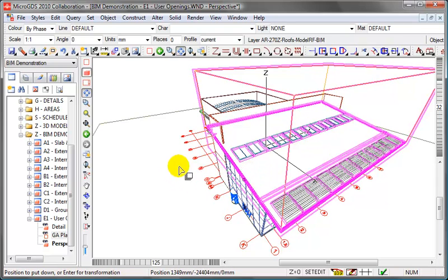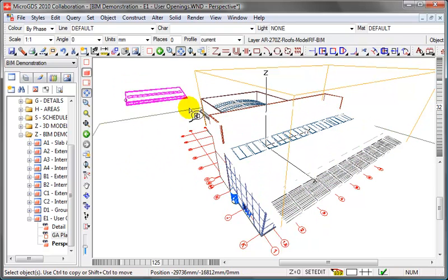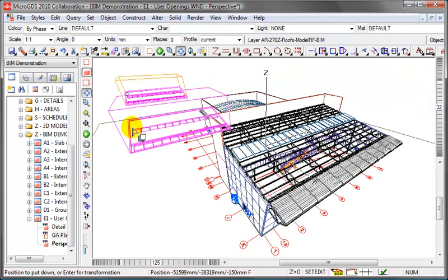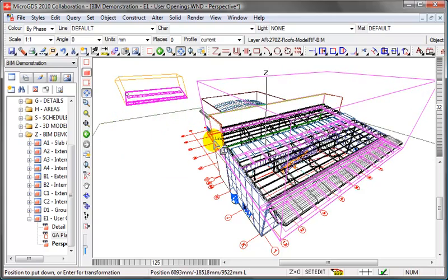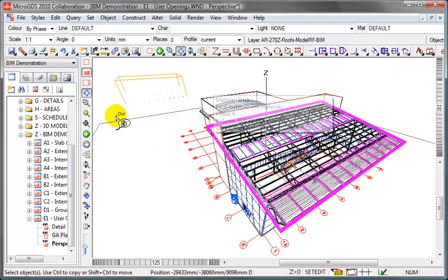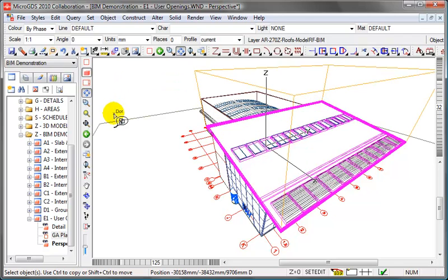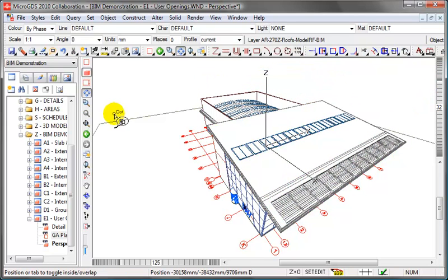We can then move the object away, and then using an origin snap, an O snap on the roof, and I've programmed my right mouse button with origin snap, and then an M snap on the wall, we can bring it back into position. It'll take a little moment to think about that, and then quite cheerfully it chops off a section of wall that's coincident with the cutter primitive that we've created.